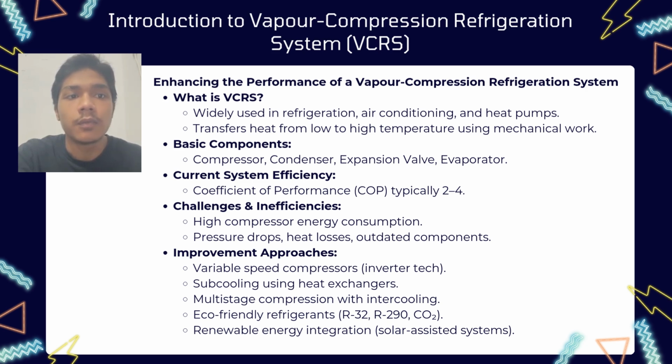Many vapor compression systems operate with a COP, coefficient of performance, between 2 to 4. However, this efficiency is often limited due to several issues such as high compression power consumption, pressure drop, heat loss, and the use of outdated or fixed speed components.